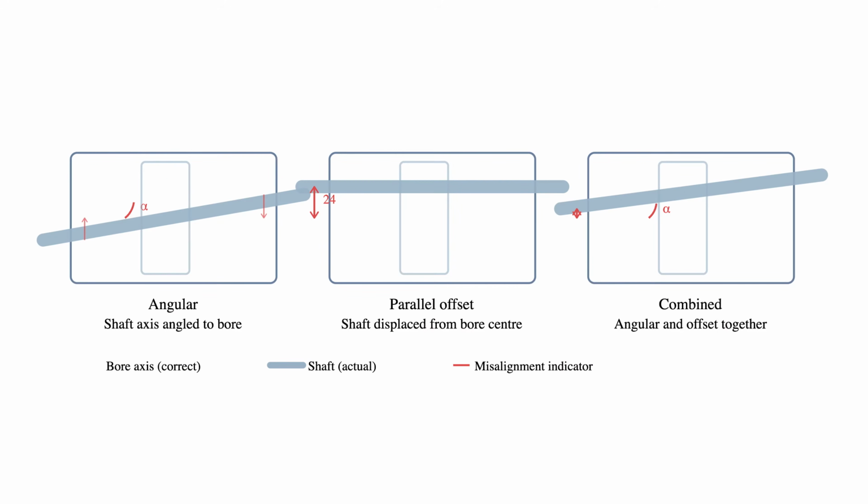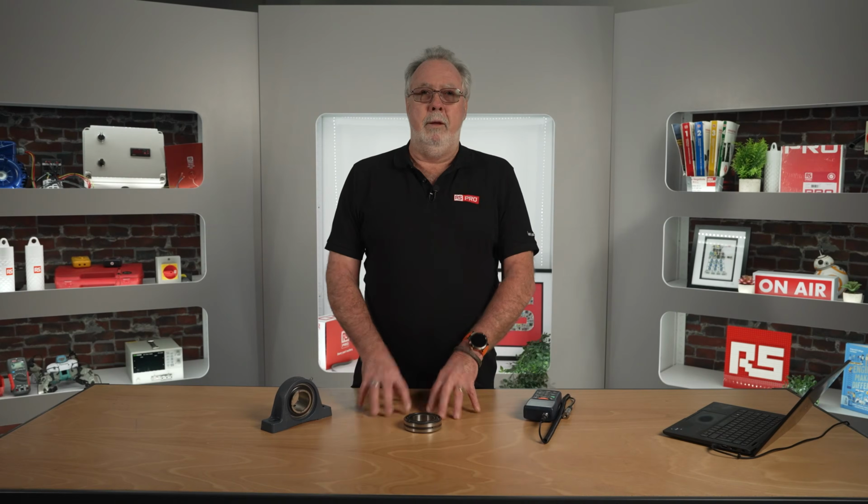When a bearing fails, it is generally a symptom of something greater. Is the shaft bent? Is it misaligned to the coupling, actually vertically and parallel? Is the motor shaft straight? Are the motor bearings good? Is the motor seating correct? Are the nuts and bolts tightened down? Can it move? Those are the things we need to look at in the drivetrain.